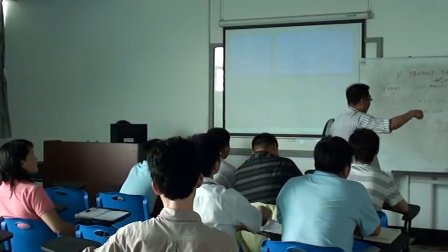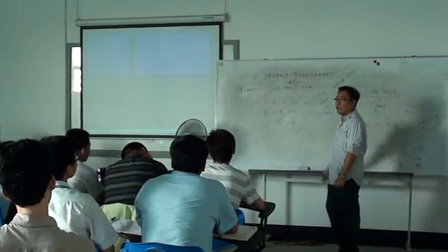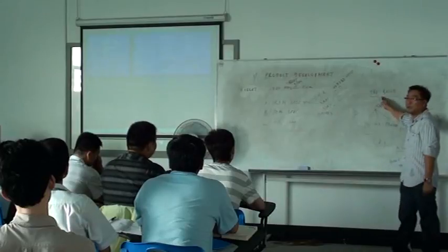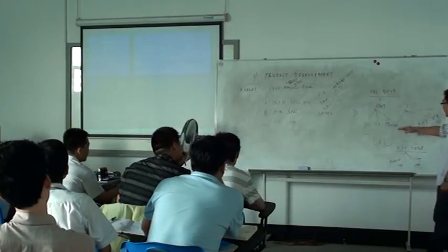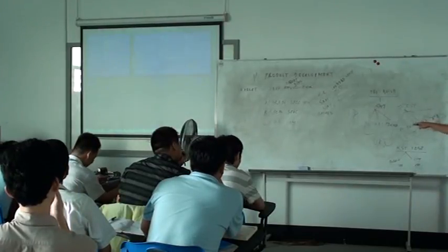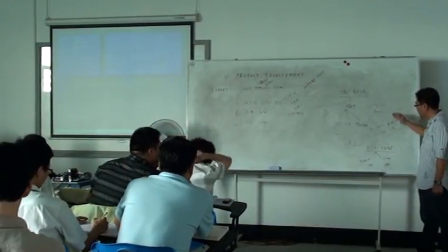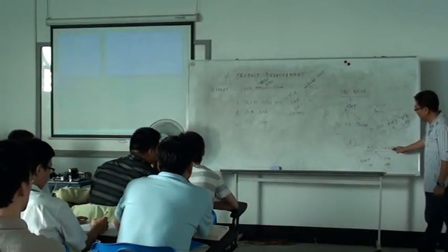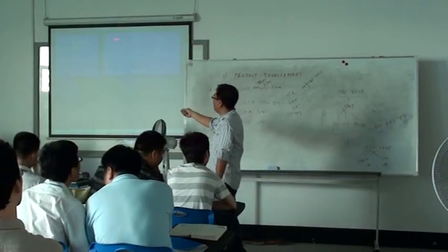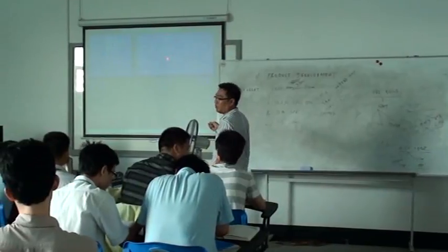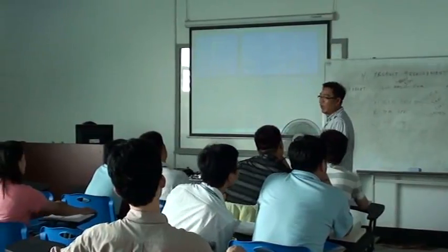So all this development takes a lot of time to select the chip. It takes time to select the right PCB. And it takes time to do a prototype build, different lots. After the prototype build passes, we test different motherboards for compatibility to make sure we have the right SPD, the right motherboard, and the right speed. And then the final one, we use the IRT test, burn-in test. So this is all the memory functional test.